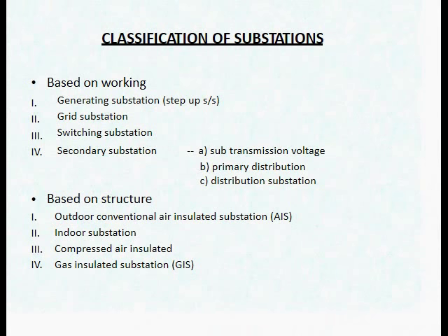Before starting with the substation equipment, let's describe what a substation is and what the difference is between a substation and a switchyard. Many people get confused about what is a switchyard and what is a substation. So let's clarify this first. Yard means field. Where all the equipments are mounted or placed, that field is called the switchyard. And the whole area including the control room building and other buildings, if available, the whole place is called the substation. So a switchyard is a part of a substation, but a substation is not part of a switchyard.